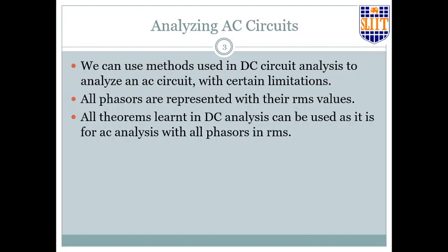So phasors are represented with their RMS values. We will be working basically in the phasor domain, right? Instead of DC domains, all techniques that were used in DC analysis will now be used with AC analysis, with all phasors or RMS values, right?